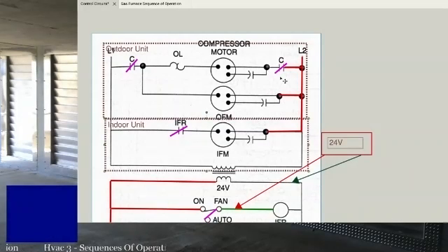I've seen crappy factory connections at compressor terminals, especially if they got those flag spades that we saw when we went over wiring connections. If it's got those flag spade terminals, then the wires can end up rubbing on them and short something out there, and that'll give you a bad wire connection. So that's bonus. There's one more thing that can be wrong though, and what would that be?